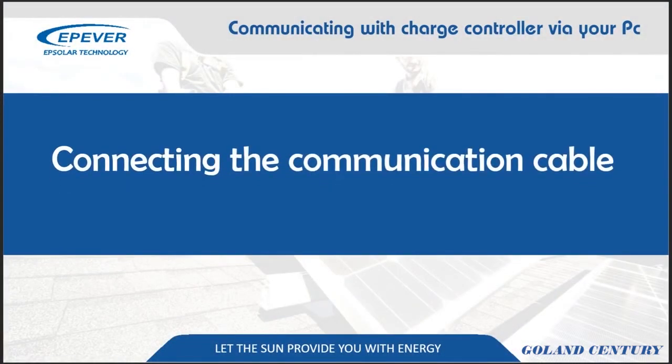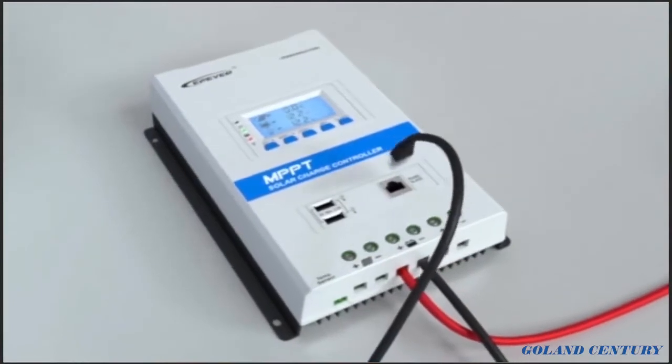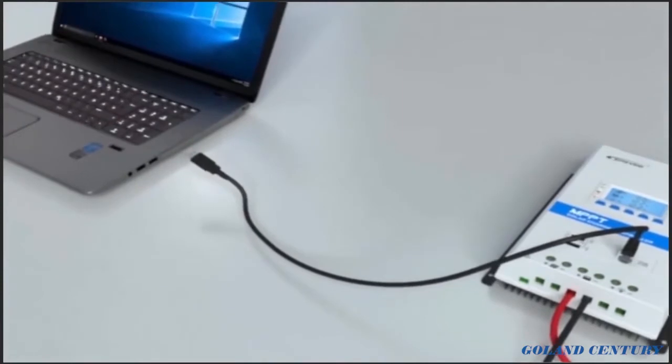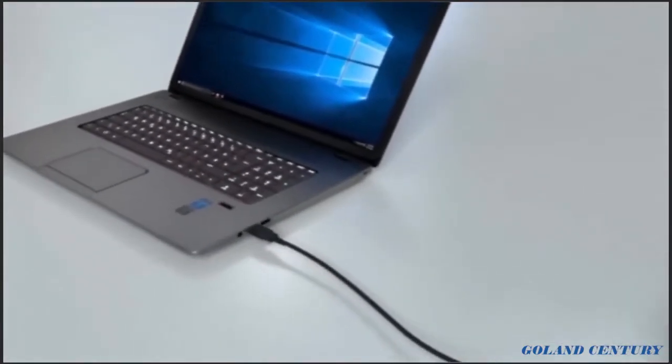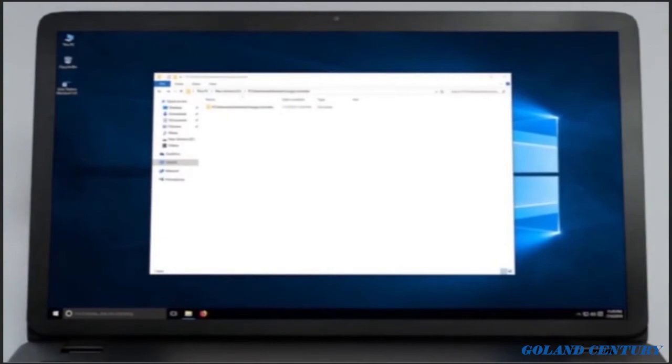Connecting the communication cable. Connect the network cable to RS485 port in charge controller. Connect the USB plug of the communication cable to your PC or laptop.